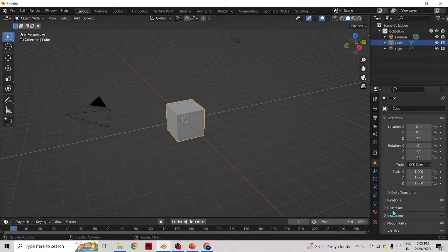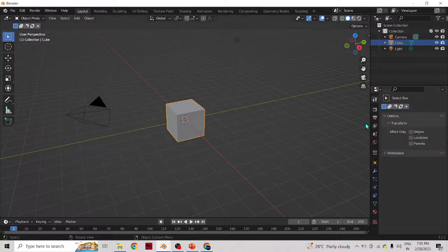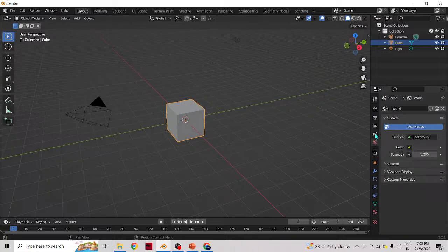In the properties panel itself, we explored different types of properties, and we also went through how to change the measurement unit, and how to bring in colors for the elements, and all those things were also a part of the properties panel which is located over here.